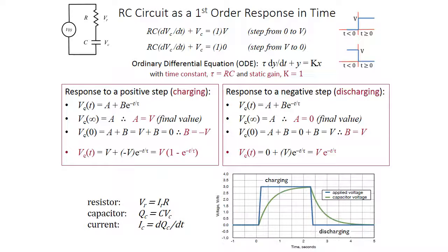What our resistor and capacitor in the circuit are doing is they're smoothing those sharp changes. They're smoothing those impulses. So that step up, that sharp increase, is actually smoothed out slowly in order to get to the top. And then same with that sharp decrease, that's smoothed out slowly to get to the bottom. And there's a lot of times in circuits and filtering of circuits where we want to smooth the circuits out because maybe we have a really fast, sharp impulse up and down, and we don't really want that full impulse.